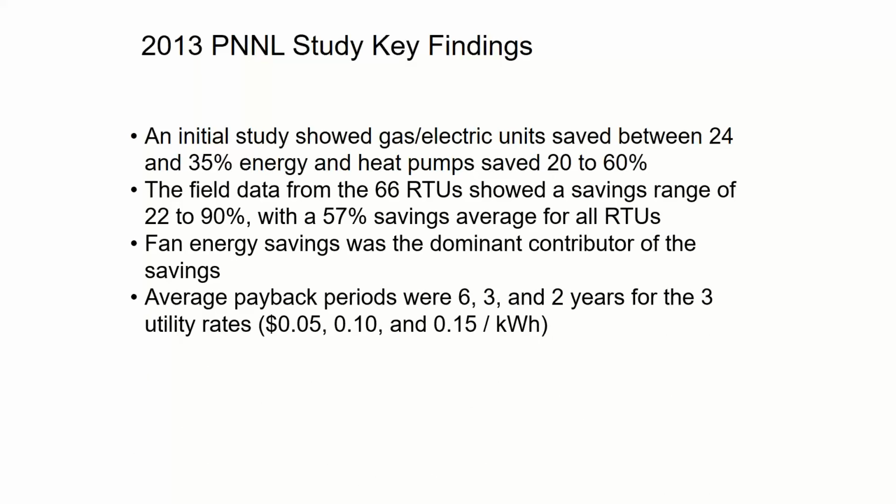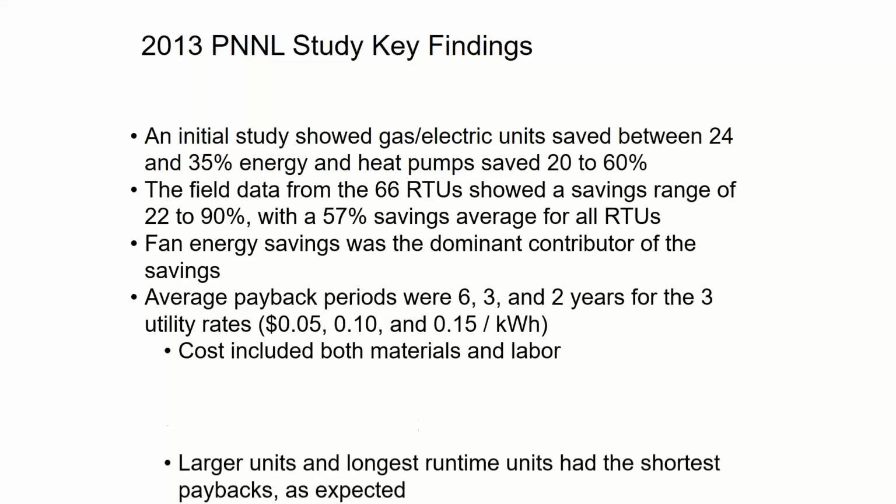To make things a little bit more palatable for end users, they did a comparison in regards to the electric rates that various areas of the country might have and how fast that would affect paybacks. So around here, we're probably around the 10 cents per kilowatt hour for most of our utilities in this area. When you take into account buying the energy, distributing the energy, taxes, fees, and everything, we're in that 10 to 13 cent range. So that probably means we're in that 2.5-ish to 3-year payback range based on the utility rates that we have. All the payback discussions included both the materials and labor.